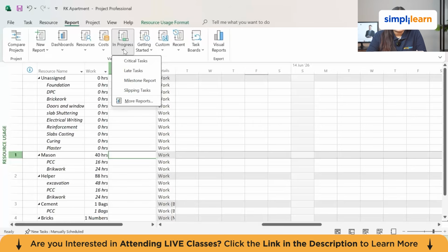The Gantt chart printout is a separate capability, and it is still a standard deliverable for construction program submission. Clients, employers, and regulatory authorities expect the printed Gantt chart. MS Project can provide you submission quality output, but it requires some setup. You need to control the date range being shown, whether each column represents a day, a week, a month, and the page header and footer. Set these up once, save the view, and every subsequent print will be consistent.